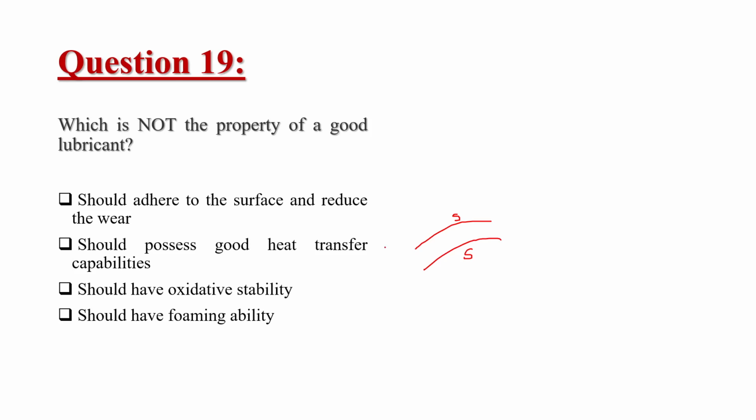Suppose we have some kind of a flat plate. When we are having a flow, a boundary layer will be created, and as we move along, say for example this is the x direction and it is starting from here. As we move along this plate, we know that the boundary layer will be growing, correct? So the thickness of a boundary layer increases with the distance x from the leading edge. If this is the leading edge and we have some distance x, then with increasing x we will have a thicker boundary layer. This is the boundary layer thickness delta. So this will increase,